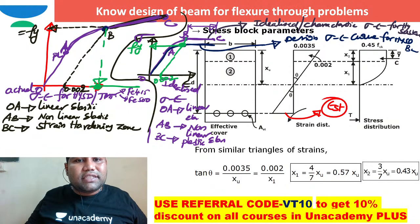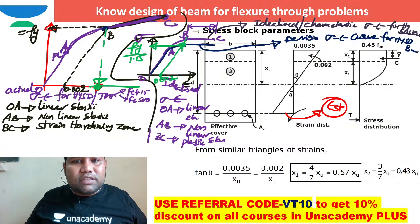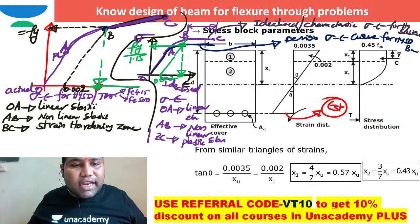What is the design stress? fy by 1.15. Corresponding to the design stress, what is the strain? This is the design strain, the strain in steel in the tension zone at the time of failure.